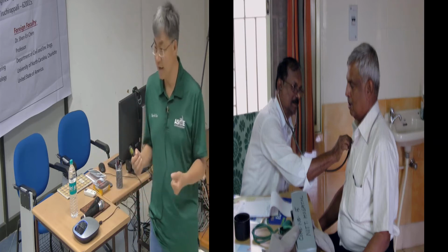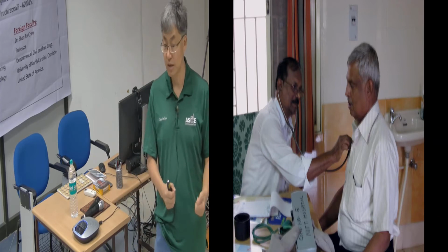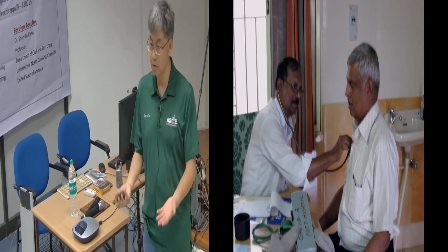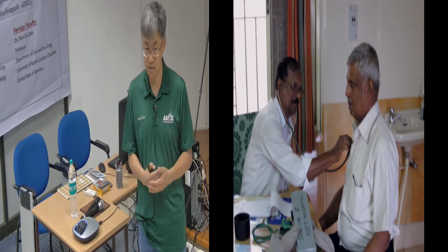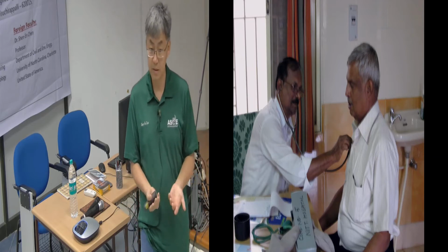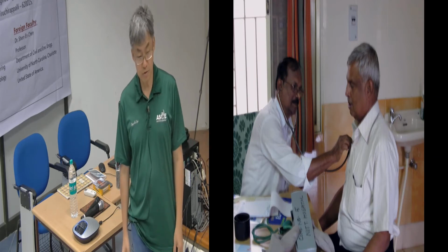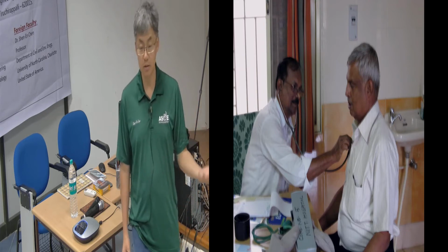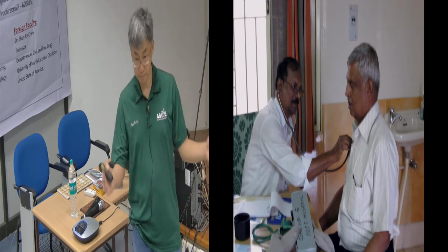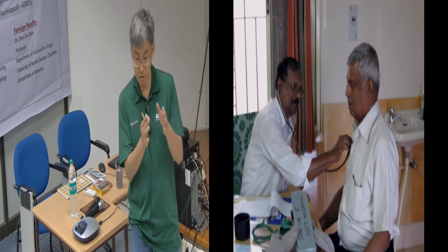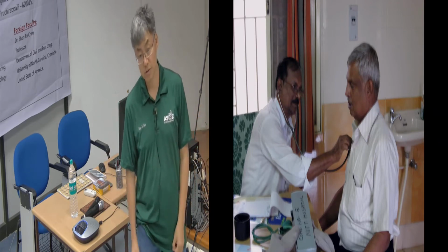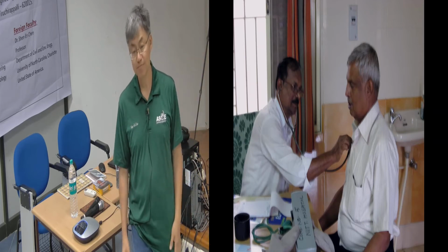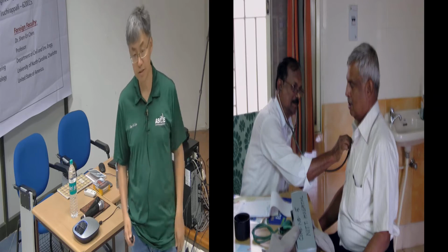They just know that, hey, I have this very powerful instrument I want to use, and it costs the client a lot of money. So my colleague and I were arguing with them, suggesting that you should use something else. So what is the specific application for this GPR? Ground penetrating radar is good for density measurements for pavements. Even in the tunnel case, for the tunnel lining, whether the lining is good or not, if it's of sufficient thickness, you can use ground penetrating radar. But whenever there is groundwater in the back, then it changes. And rebar is another application.